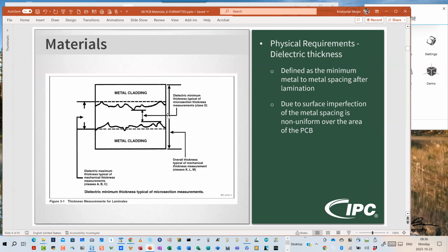But suffice it to say, in order for adhesives, whether that's super glue, Elmer's glue, the sticky backing of duct tape, epoxy, urethane, acrylic, it doesn't matter, they all work exactly the same way. In their liquid state, they look for little nooks and cracks and crannies in the surface imperfections or surface roughness here.